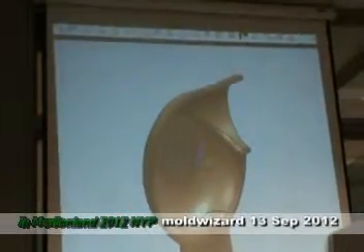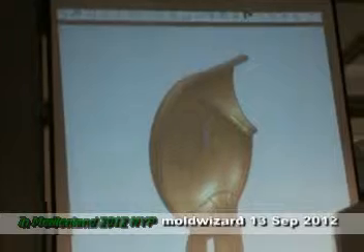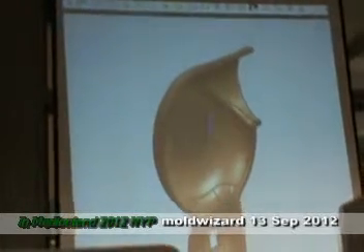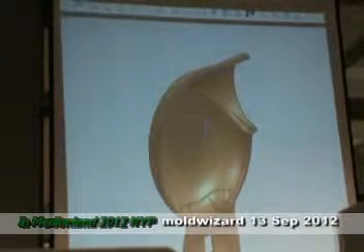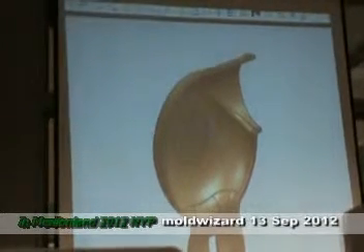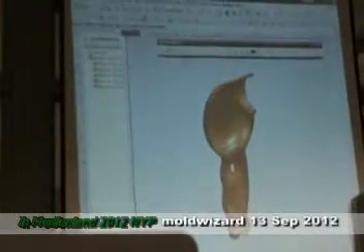According to the current image, this Z direction is pointing upward. But for us, that will be a problem, because I cannot eject the product following this direction. So I need to rotate, right? That is something we do here.